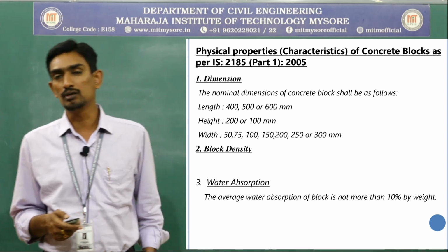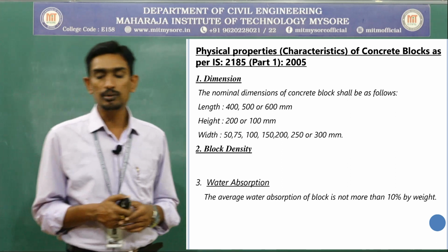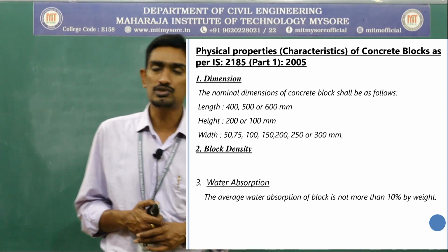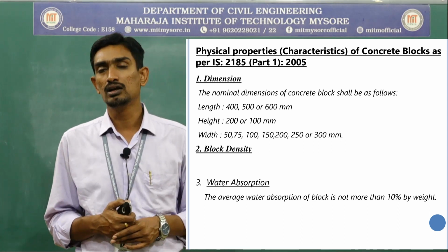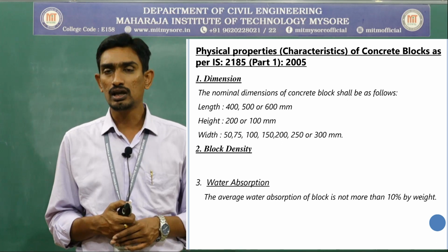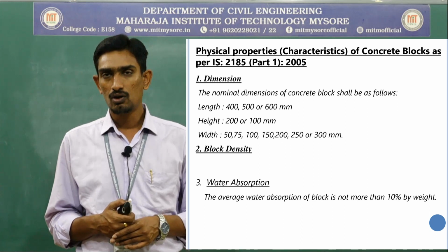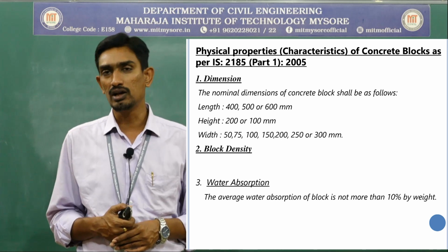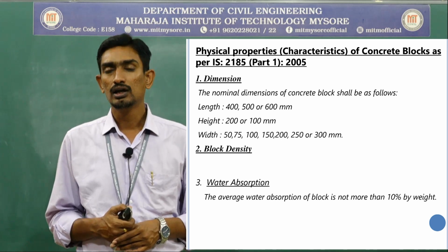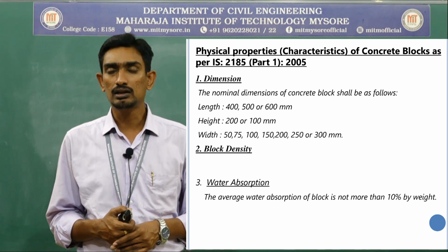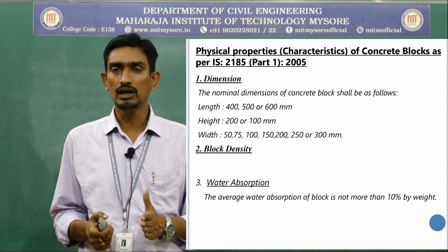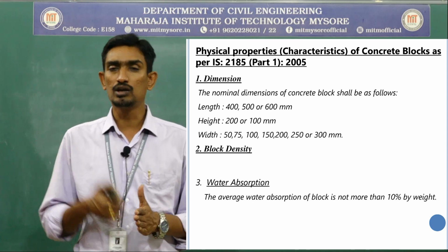It should not be more than 10%. I think I have not been told regarding how exactly the water absorption will be conducted. The water absorption will be calculated by, first, take a required size of the brick and take the weight of that block, immerse it in the water for 24 hours, then take it out, drain off the water and take the weight. That means first day you will take the dry weight, completely removing the moisture, and take the weight.